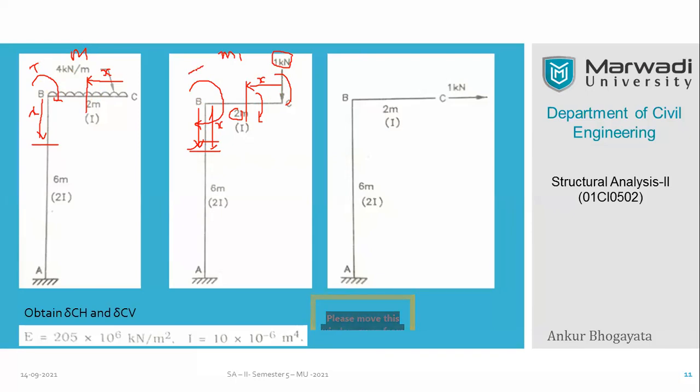So here again, you have total moment due to this unit load. In this case, there is no such moment for this, but when you come down here, take an X distance like this, there is a very well possibility to take the moment of this force 1, and the perpendicular distance is X.